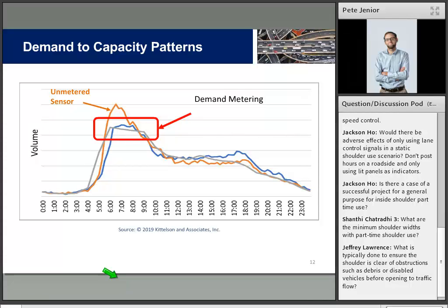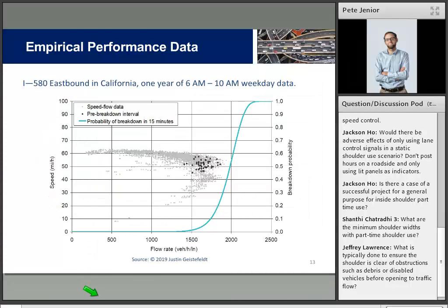What we're looking at here is an in-roadway sensor, or it could be on a pole, but it's something in the field that the agency maintains. You can see here three different volume profiles from three different sensors. For these two, the sensors were placed in a location where a bottleneck metered demand. Here is a sensor placed where it's picking up the full demand, as opposed to just the volume that's able to pass through. It's not metered. So the placement of sensors is a key factor for an agency to consider when they're using their field-based data.